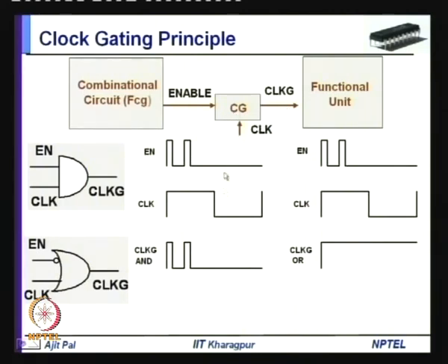As a result, this functional unit may malfunction, because you may be latching some data with the help of this clock. So, you will be latching some unnecessary data, or if it is a combinational circuit, then it will lead to glitching power dissipation. So, in either way it is not acceptable to us.